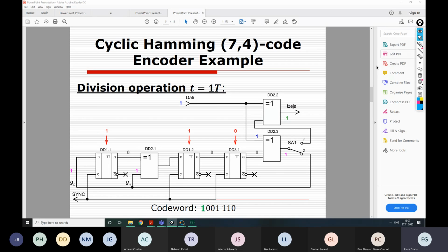Then in the next time interval, another code word symbol comes, 0, which is directly output, and we can see here that we already have output 2 symbols, right? And it is coming through this feedback network as a sum here. Our previous values here, which we calculated at the time 1t, were 1, 1, 0, right? So this 0 comes here, this 1 will come here.